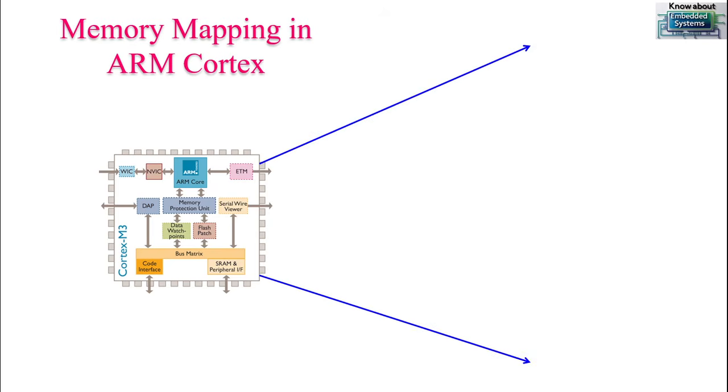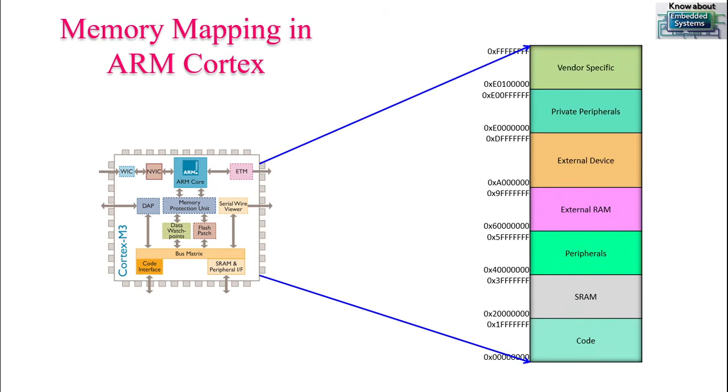So how does it look? This is how it looks. We have a processor on one end, this is your ARM Cortex processor, and here you can see the memory. The chip designers are going to integrate the processor with this memory. And this memory is totally 4 GB, because for almost all 32-bit processors we can interface up to 4 GB of memory in this fashion.